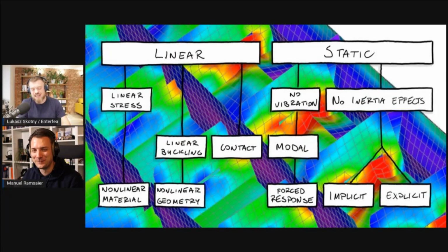The thing is that there is always a discussion, and then someone says, no, we'll do a linear analysis with linear contact. And then you're like, no, it's not linear. But the solver is linear, like, you can buy a linear solver bundle that does solve contact, right? It becomes beautifully complicated, not on the level of what is true, but what people call it. I think what's more important is not the name itself. What's important is actually what the thing does. And whether you're doing linear analysis or not, if two things can touch, you will have contact.